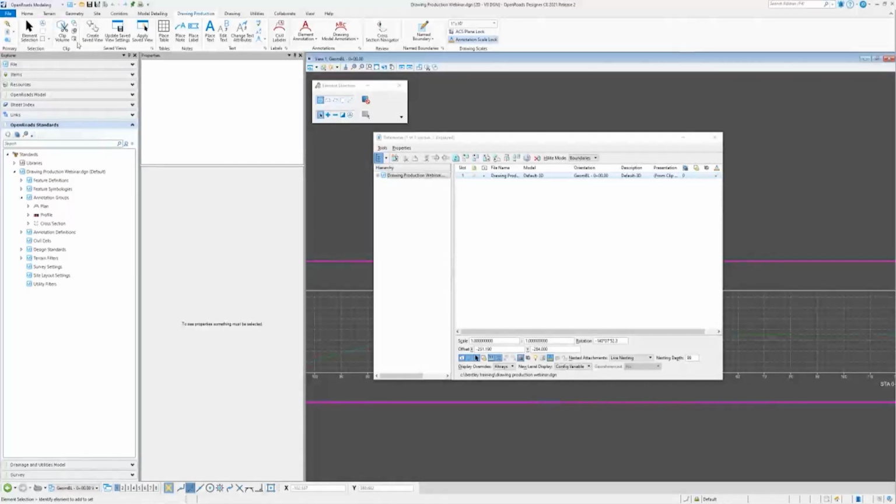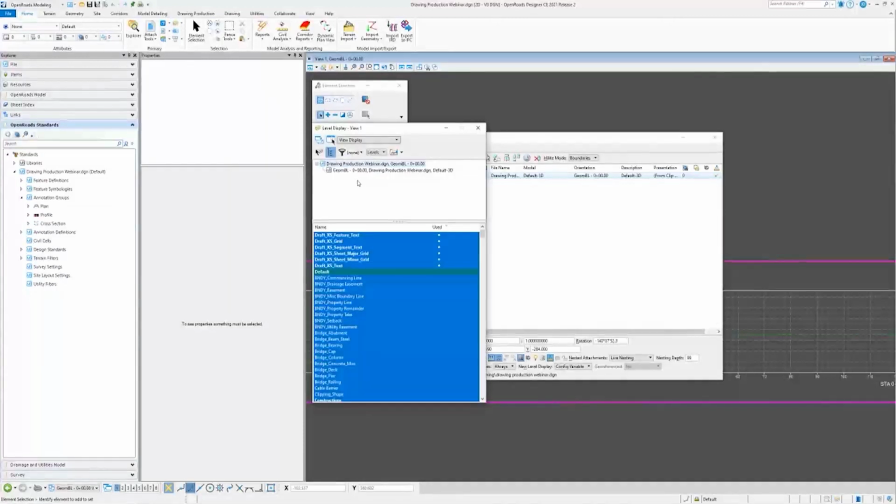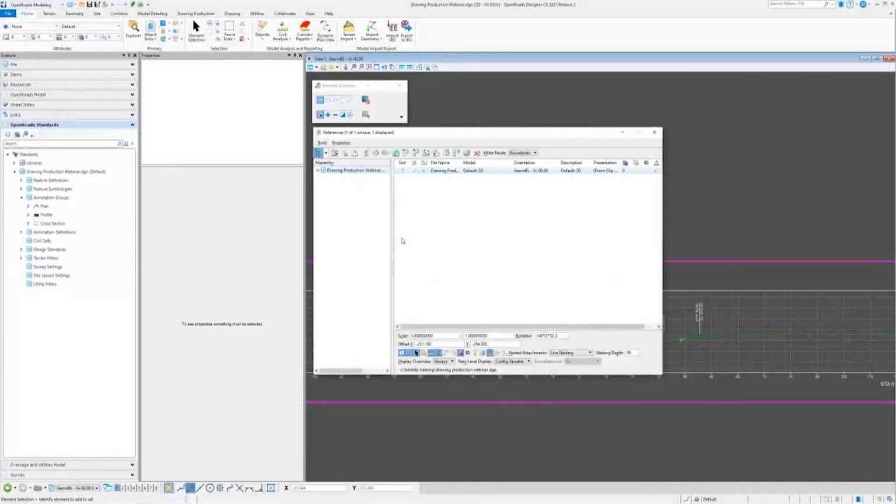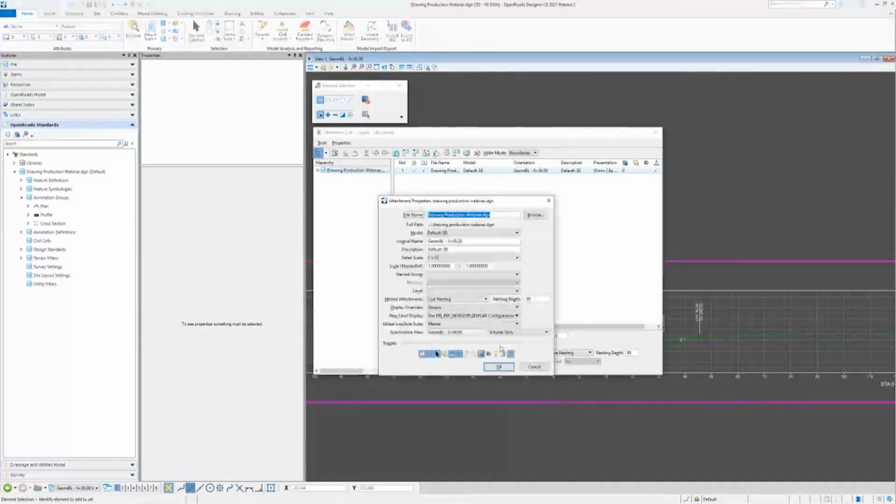Anything you change here in your design will update all the way through to your sheet model. But yes, I would say there's probably a few other ways. I believe in the levels display dialog themselves, you can usually click through multiple models here, especially if they're referenced, and you can turn off anything. But if you're talking all sheet models all at once, this I think would be on a more individual level basis. But the settings from design model you could easily control. You can change that at any time too. So you can easily control the levels from the design model and have that update through to all your sheets.